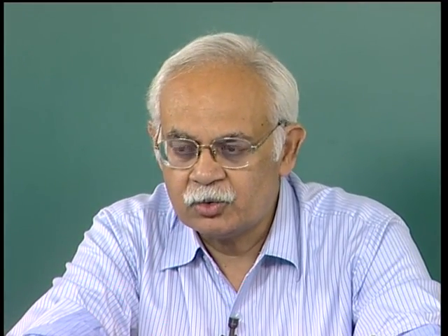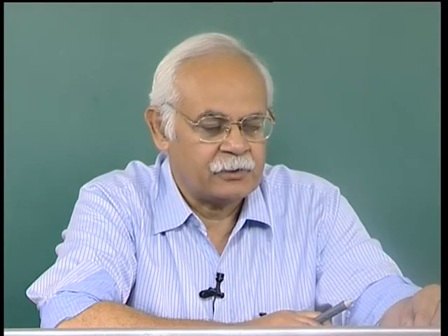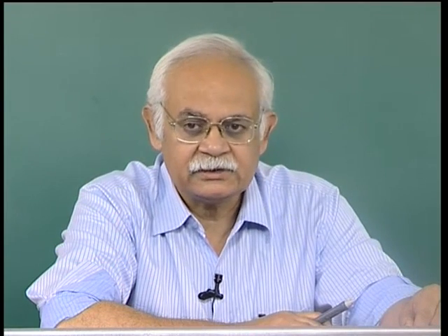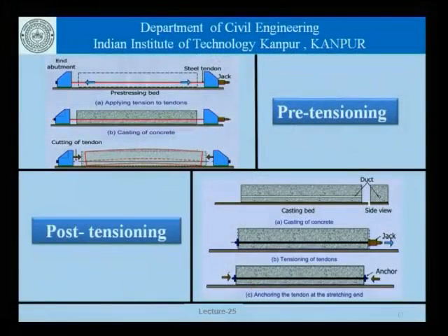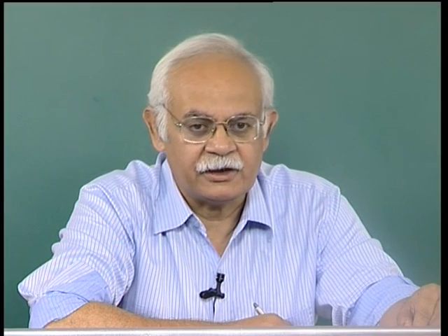But we know that in concrete members, particularly beams and slabs, the reinforcement at the bottom is more than at the top in normal simply supported cases and so on, apart from cantilevers where the situation is reversed. But not getting into that detail, the fact remains that the degree of restraint to the expansion is higher where the reinforcement is higher, and that is what would cause a situation which is close to this.